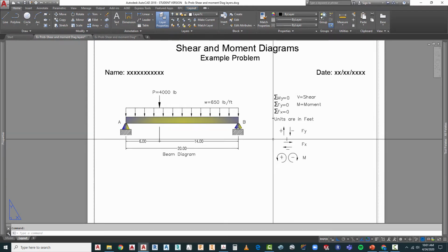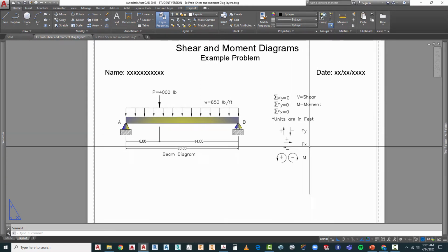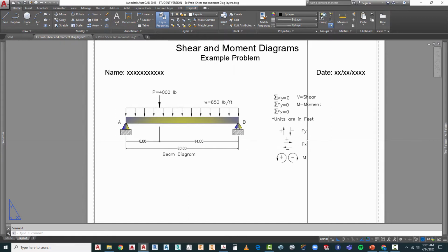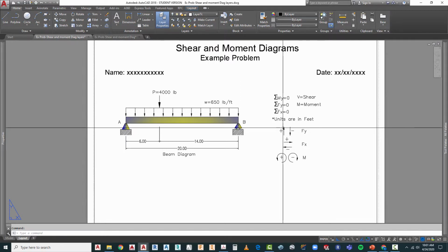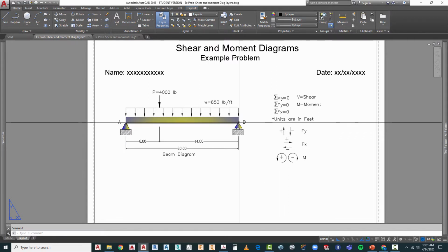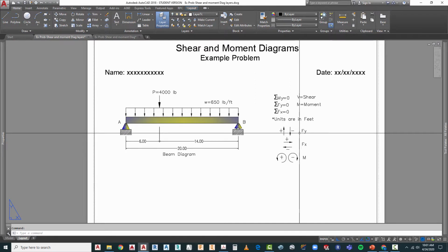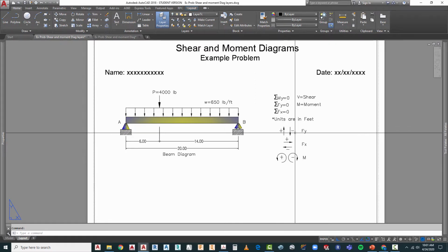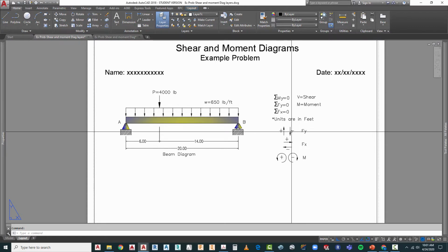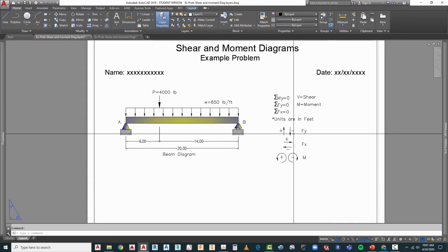What is also extremely important when we apply these equations is that we know the sign convention for the force. As an example, an upward force, which might be the reaction force at the support, is considered positive, while a downward force is considered negative. So when we put it into the equations, we'll know whether to use a negative or a positive value for that force.